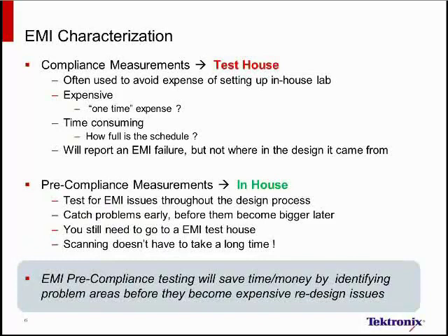When it comes to EMI characterization, we basically have two perspectives. We have compliance and pre-compliance. Compliance measurements involve a large capital outlay, not just for the equipment, but also for the physical setup. To build an anechoic chamber of 3 meters or 10 meters is very, very expensive. Big companies can support these costs, but very often smaller companies can't. So smaller companies will use an external test house to do the compliance measurements for them.